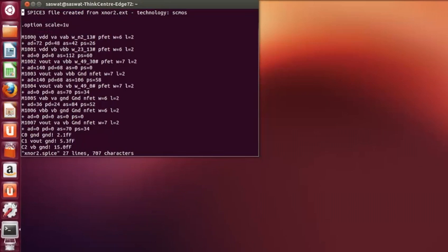This is M1000. M stands for MOSFET. This is the first PFET, that is the first P MOSFET. The W by L ratio, that is W is 6, L is 2. You can see the first two P MOSFETs have the same W by L ratio, which varies from the third P MOSFET. It's 7 and this is 2. Then this is the fourth PFET, that is 7 by 2 W by L ratio. If you remember, for the 6 by 2 ratio there are 2 P MOSFETs and the next 2 P MOSFETs have the same W by L ratio.